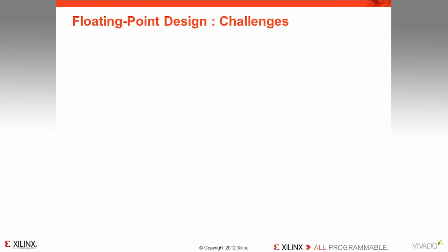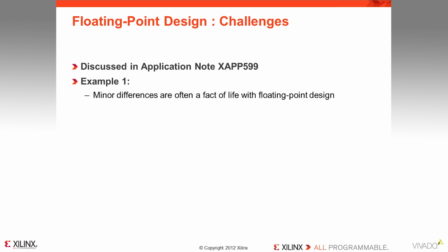For designers who are new to floating point design, or for designers who have only ever used logic cores in the past, there are some challenges to be aware of. The Vivado application note 599 covers all of the potential challenges. It provides a detailed introduction to performing floating point design with C and walks you through each of the challenges with detailed explanations. For example, we have already mentioned in this short video the differences between some of the C implementations and RTL implementations.